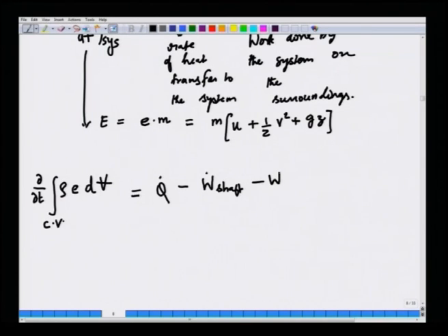Then we also had, in general, a shear work done at the entry and exit through the control surfaces, but we also said that that can normally be set to 0 by choosing the control surface perpendicular to the flow velocities. Okay. But this is not all.